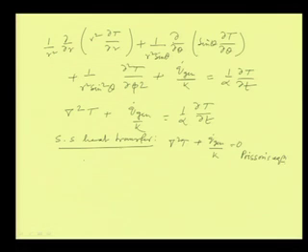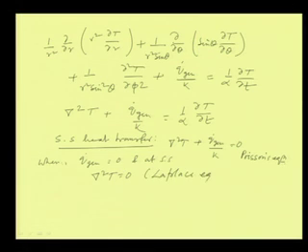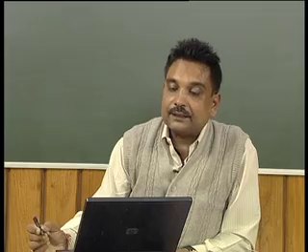When there is no heat generation, that means q dot generation equal to 0, and at steady state, grad square T equals 0. This is called Laplace equation. In fact, these are the two equations which are the simplified form of the heat transfer situations.